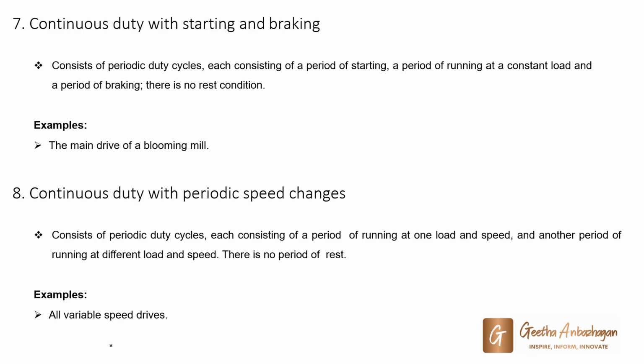Next, we have continuous duty with starting and braking. It consists of a period of starting, a period of running, and a period of electric braking. Here, the period of rest is negligible. This type of duty can be accomplished by single or three-phase induction motors. And the example here is the main drive of a blooming mill.